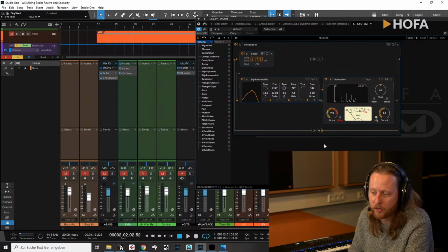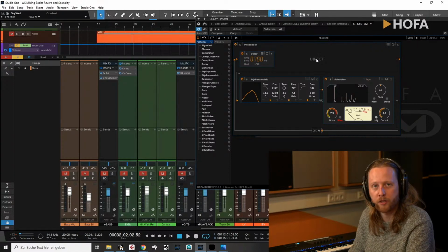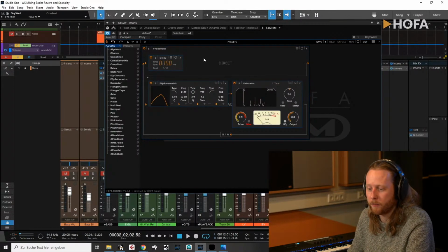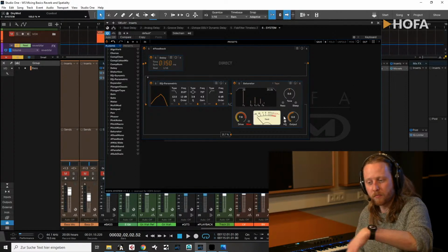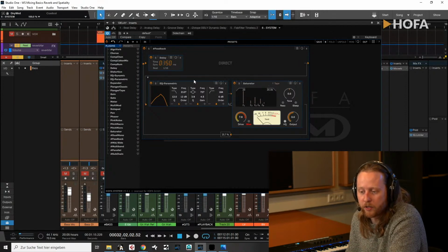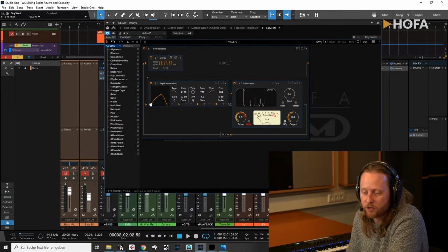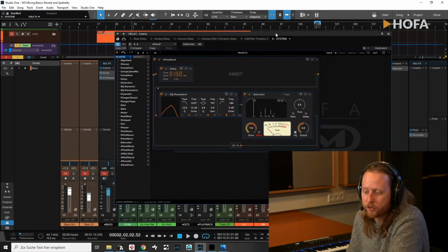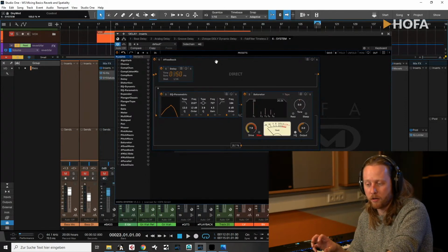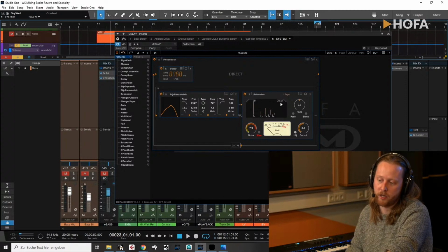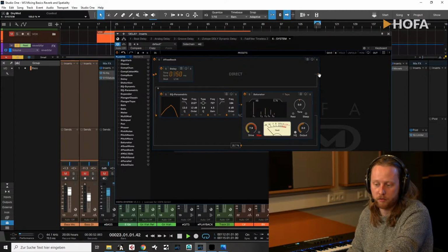This means the signal gets fed back by 25%, so every iteration of the signal that gets fed back will get a little more filter, and a little more saturation each time it goes through there. So each iteration will be a little duller and a little more distorted. This is kind of what happens in a tape echo as well, right?